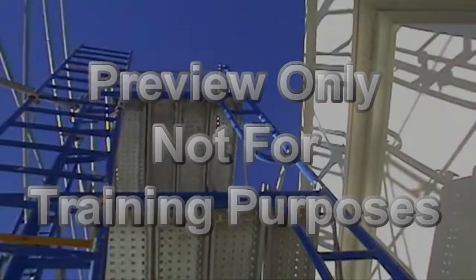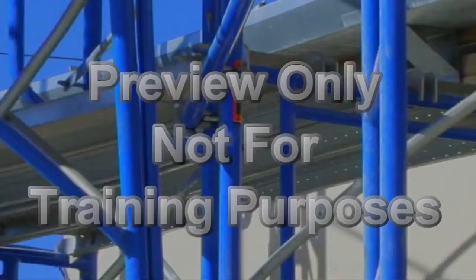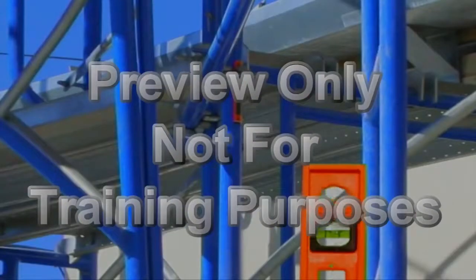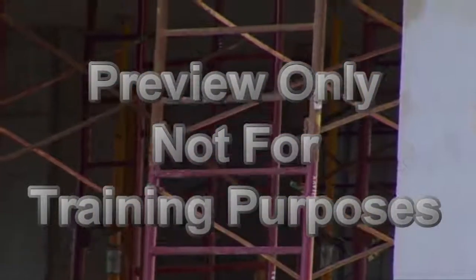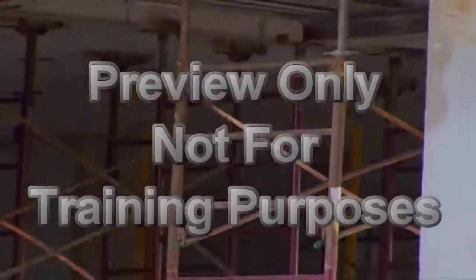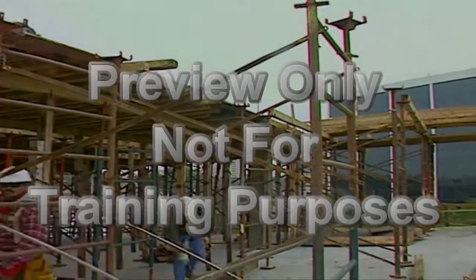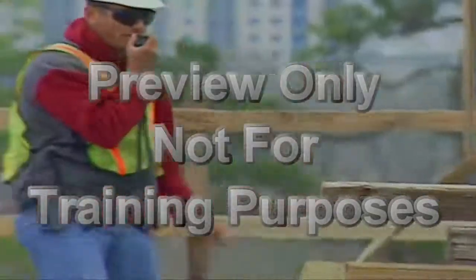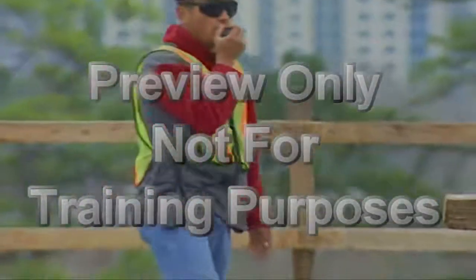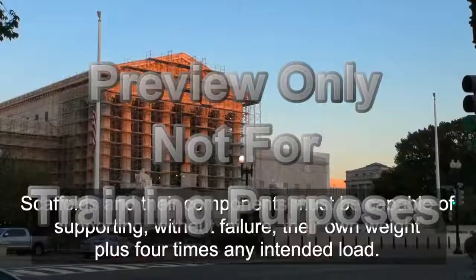Poles, frames, and uprights must be plumb and braced to prevent swaying and displacement. Use of a level is the best way to achieve the desired right angles. The integrity of the support structure of scaffolds is very important. As noted earlier, scaffolds can only be erected, moved, dismantled, and/or altered under the supervision of a competent person and only by experienced and trained employees selected by the competent person.